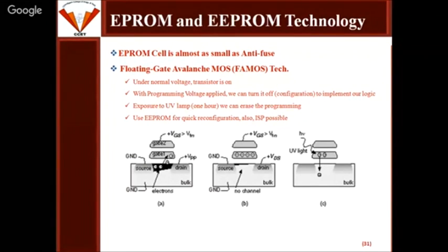But that connection has to be permanent in case of ROM. And that is where you have a gate that is floating type, and when you expose it to the light... I'm not talking about the light. UV is separate. We are talking about electrically erasable. You're saying that a normal MOSFET is not going to work. A normal MOSFET is used for RAM, not for ROM.